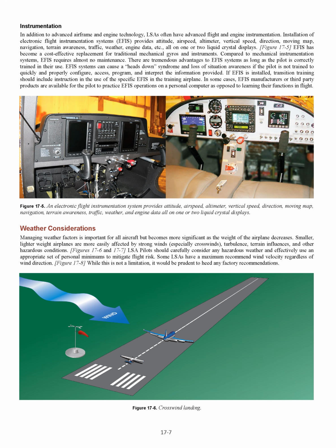Instrumentation. In addition to advanced airframe and engine technology, LSAs often have advanced flight and engine instrumentation. Installation of electronic flight instrumentation systems, EFIS, provides attitude, airspeed, altimeter, vertical speed, direction, moving map, navigation, terrain awareness, traffic, weather, engine data, etc., all on one or two liquid crystal displays. EFIS has become a cost-effective replacement for traditional mechanical gyros and instruments. Compared to mechanical instrumentation systems, EFIS requires almost no maintenance.